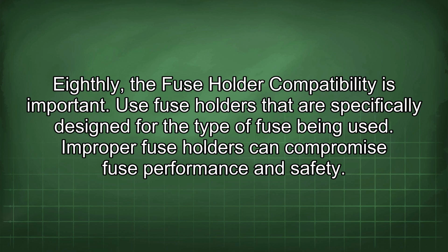Eighthly, the fuse holder compatibility is important. Use fuse holders that are specifically designed for the type of fuse being used. Improper fuse holders can compromise fuse performance and safety.